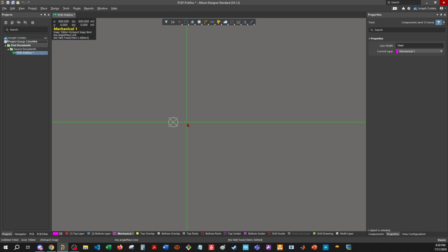I'm going to left click here, and I'm going to change the way this draws. Right now it's drawing exactly the shortest distance, straight to my mouse cursor. Hold Shift, press Space. You'll see it changes the routing. I'm going to do that again, holding Shift and pressing Space. Not what I want quite yet. Hold Shift, press Space. And now you'll see I have the drawing style where it goes in right angles.